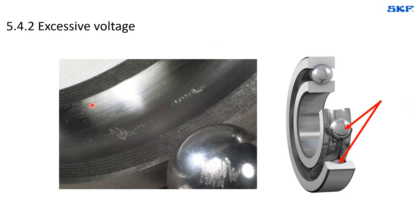Excessive voltage is a problem that, of course, can typically happen when repairs and welding are being done and the electricity flows through the bearing. In this example, we see a very strange phenomenon: the electric current has created this zigzag on the surface of the ball and the outer ring of this ball bearing, but you will also see something similar on the inner ring because it has to go all the way through, and some more spots here.